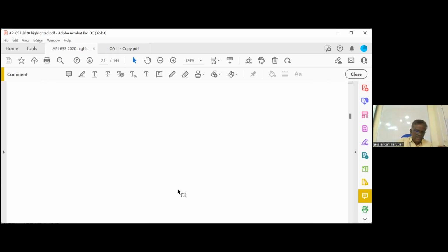Okay. And the last one is reinforcement lining. Are the lining means it's on the top side, sir? The top side lining, if the thickness is more than 50 mils, that is called a thick reinforced lining. Then it can be 0.05 inch. How many mils, sir? 50 mil. 0.05 multiplied by 1000 will result in 50 mil.